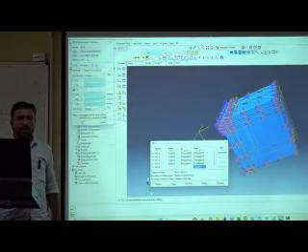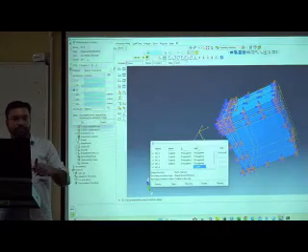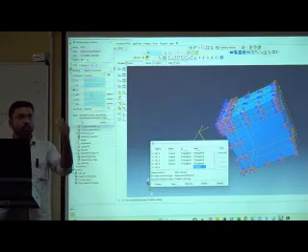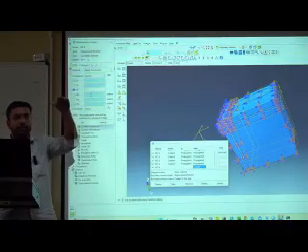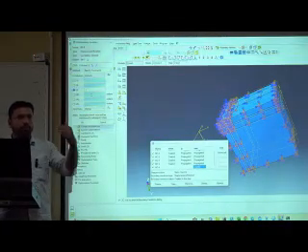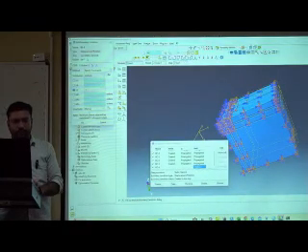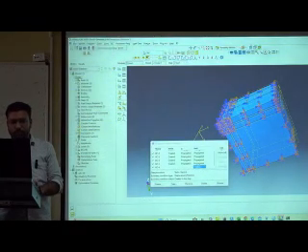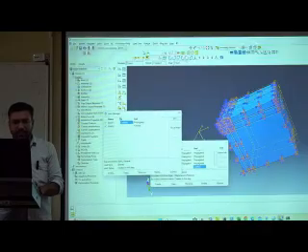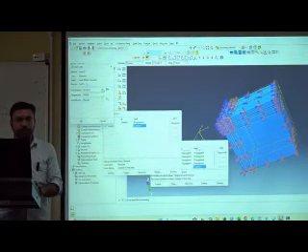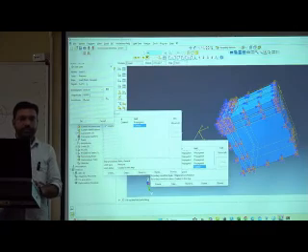So I allowed, now I am giving 1 meter as a prescribed displacement. It will go 1000 mm deep in the soil, so the load will be accordingly. Okay. So the second is, with the gravity, you can also apply the pressure. Okay, this pressure is 100 kilonewton per meter square.